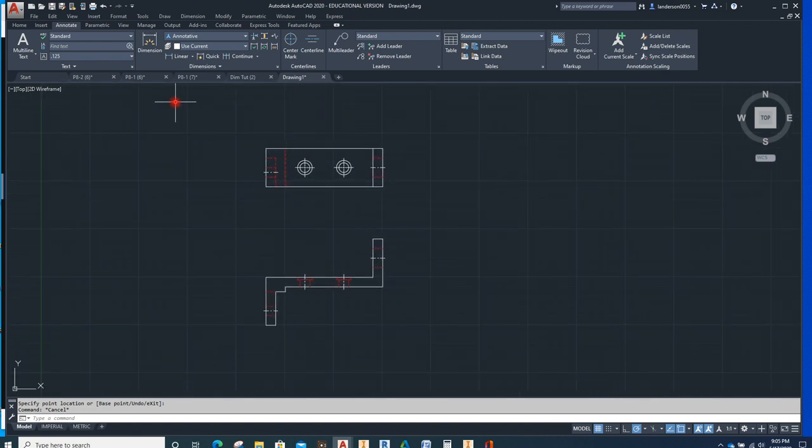Next, we draw. Now, this is where we figure out if we want to do the side view of this side or the side view of this side. Please excuse my squeaky chair. Okay, so the side view should always be the view with the fewest number of hidden lines. Okay?